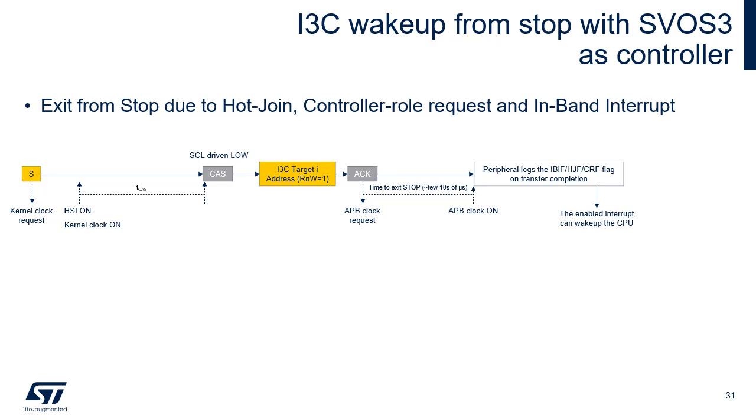There's an additional delay if the selected oscillator source for the system and APB clocks is not the same as the one driving the I3C kernel clock. If so, the system enables the source oscillator of the system clock, which gets ready after a delay.